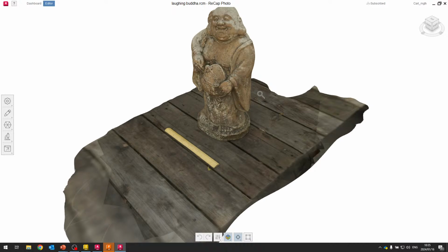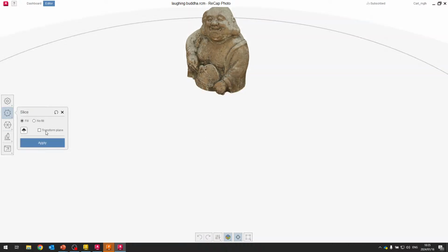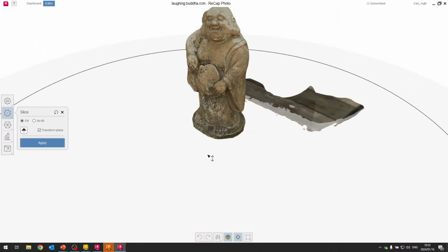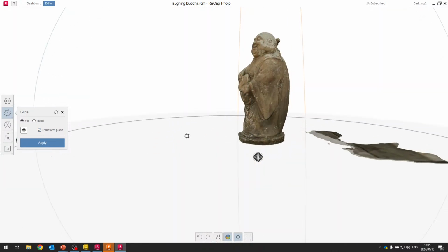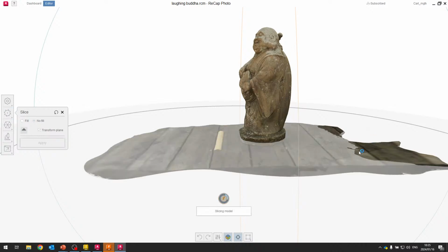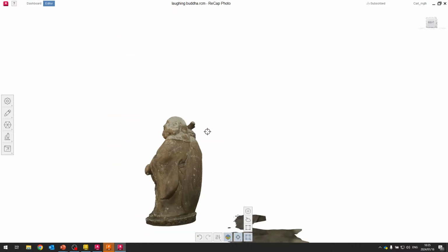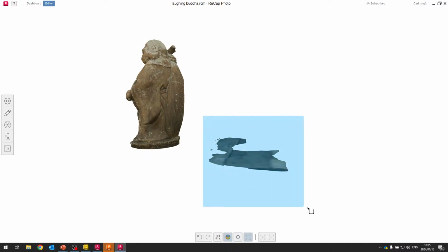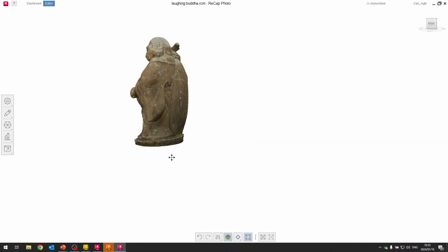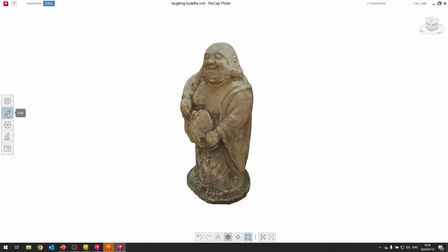$300, and we'll do the quick slice and fill. In this case, I'm going to do a no fill. I'm assuming the scan section on the right hand side there caused problems. There we go. And so what we'll do now is I'm going to go ahead here and select the box, select that region, and just delete on the keyboard to delete it. And so now I have the rest of that scan.